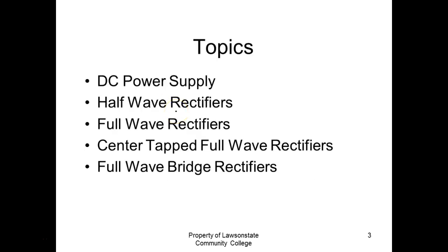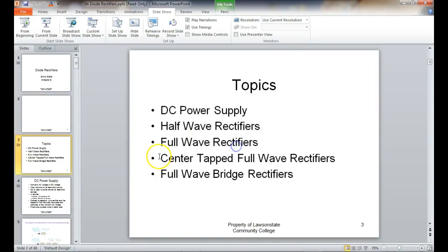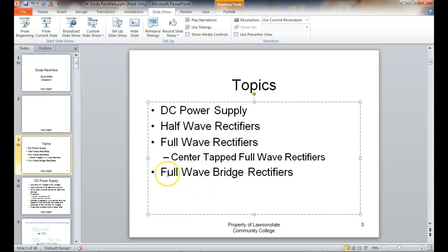So half-wave rectifiers. Y'all got any problem with half-wave rectifiers? Actually, these right here should be tabbed over, because we have two types of full wave rectifiers. We have a center tap full wave rectifier, which we looked at. It requires a center tap transformer, but it only uses 2 diodes. Everybody okay with that?